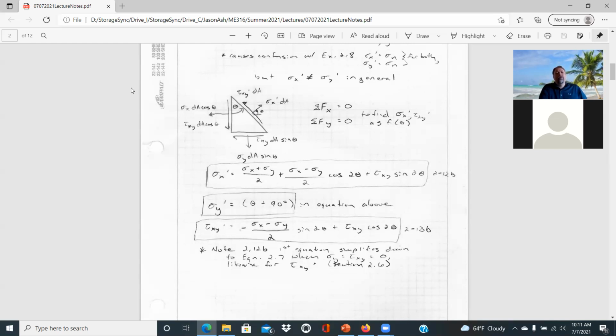And so in most cases, you're given your state of stress, or you've solved for your state of stress, and you're just looking for the stresses on a different orientation at that same location. That's our goal: summing forces in x and y equal to 0. We have all the knowns, all the original stress conditions, and we're solving for the unknowns, tau xy prime and sigma x prime, to satisfy equilibrium.